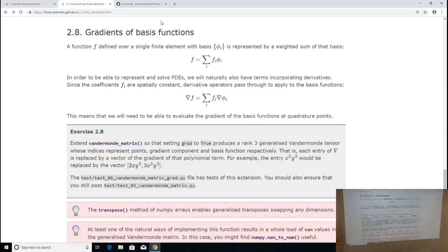So actually, the things that turn up in our expressions are functions in the finite element space, and that is to say that they are functions with respect to the basis functions. So they are weighted sums of the bases. Any function in the finite element space is the sum over the basis functions of a set of weights times the basis function values. So when I take the gradient of one of these things, well, this guy is a function of space. So in principle, it's got a gradient. That guy is just a number. So it's just a scalar multiplying the derivative.